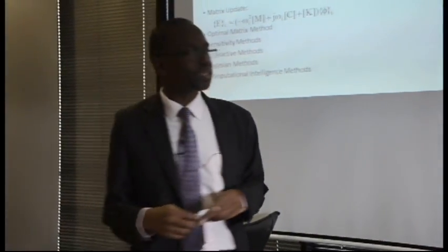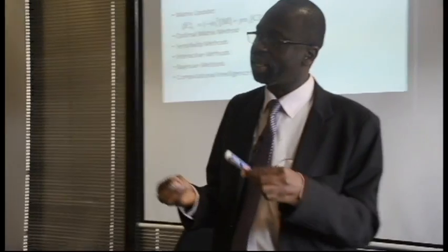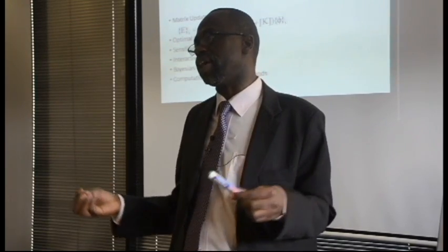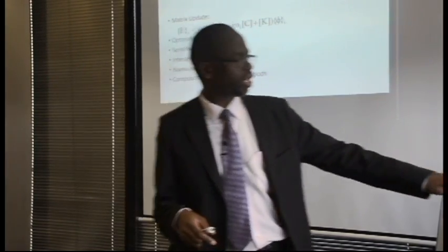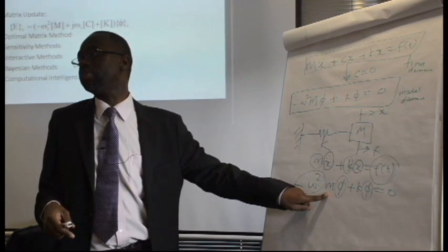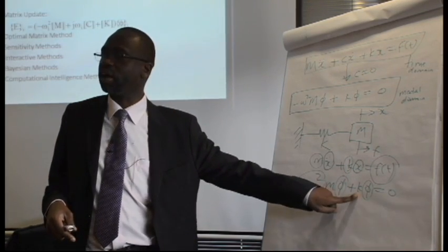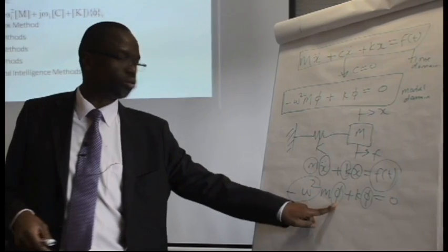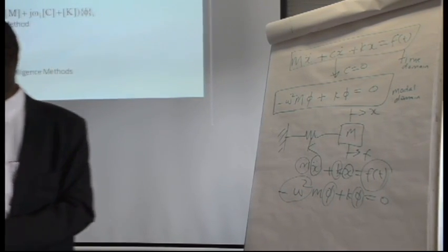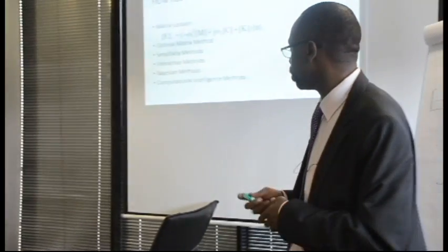So we have an optimization problem. That's what we do. You are exploiting the mathematical relations in order to identify the correct parameters of a finite element model. Of course, this is a single degree of freedom, so it is easy. But if it is a finite element model, this might be a 1,000 by 1,000 matrix, and this will be a vector of 1,000 by 1, and omega is a scalar. There are many methods that have been identified to do finite element updating.